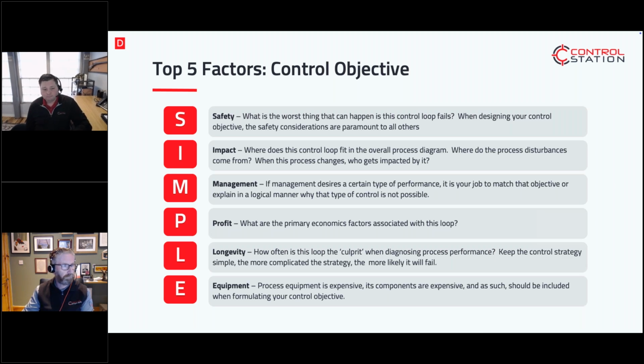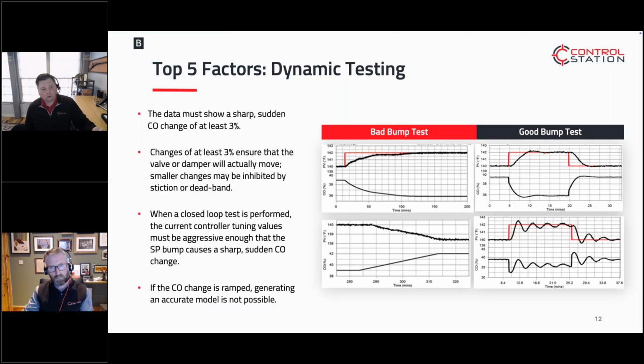And that's what we're after, because repeatability allows efficiency gains in the processes that we're doing, right? And so now that you've got the control objective, let's talk about getting data and analyzing that data to generate tunings, right? And the very first thing you have to do to be able to generate tunings is to understand the behavior of the system, the characterization of the system. Am I tuning a Ferrari or a Model T? How does it respond?